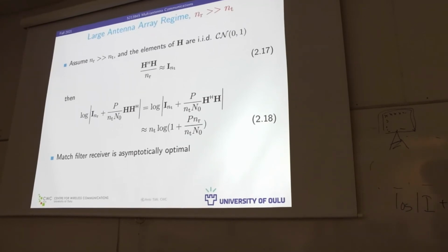So we can actually use the log rule, det(I + AB) equals det(I + BA). So now this would be N_R dimensional, equivalent to log det(I + N_T, I of N_T plus P over N_0, H Hermitian H). It's equivalent. You can check if you don't believe.